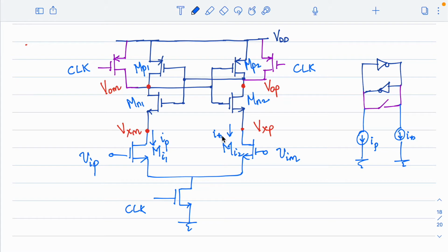Right. Now what should happen is, whenever there is a small signal available at VIP and VIM, the circuit should make a decision whether that can regenerate to 1 or regenerate to 0. Right, that is the operation we are expecting out of this. All right. So this is a clocked comparator as we mentioned.